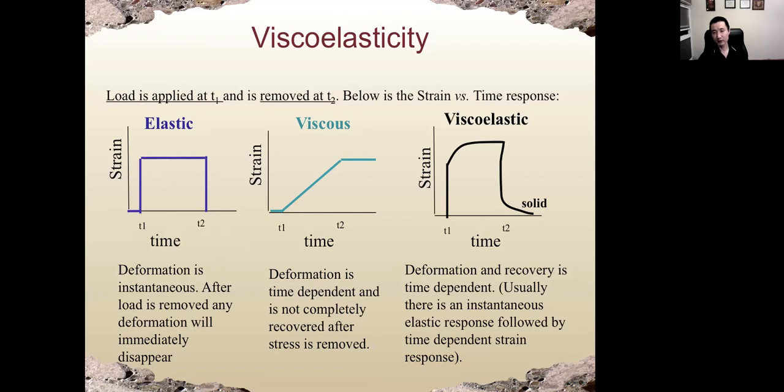Some materials such as concrete have both elastic behavior and viscous behavior. So at T1, some of the deformation is instantaneous and part of the deformation is time dependent. At T2, we remove the load and part of the deformation recovers instantaneously, but part of the recovery is time dependent.